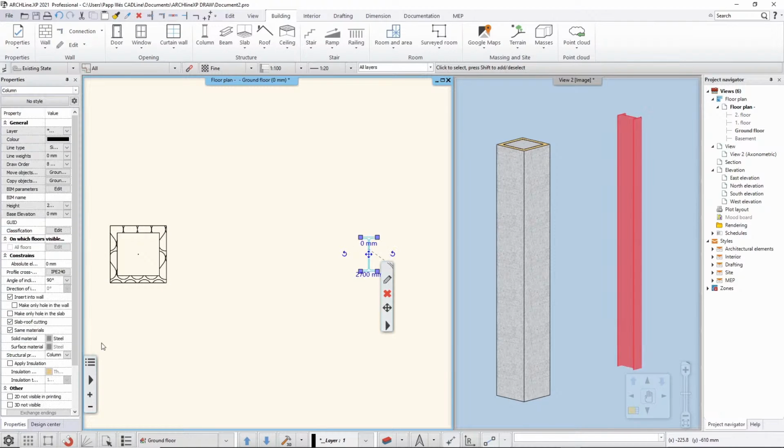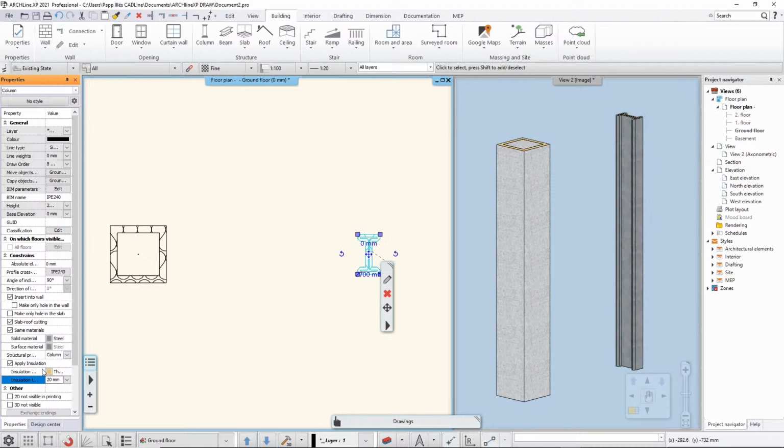So if you select that and you do the same thing, you apply this setting to this item, and in case that did not appear, it's because perhaps the coating is too thick, and then you can just disable that, or you can just change the thickness to something else that will work with this one. So for example, in this case, I need to reduce the thickness to, I don't know, something like 20 millimeters or 30 millimeters. And when I hit enter, now the software will add this extra layer of coating here.